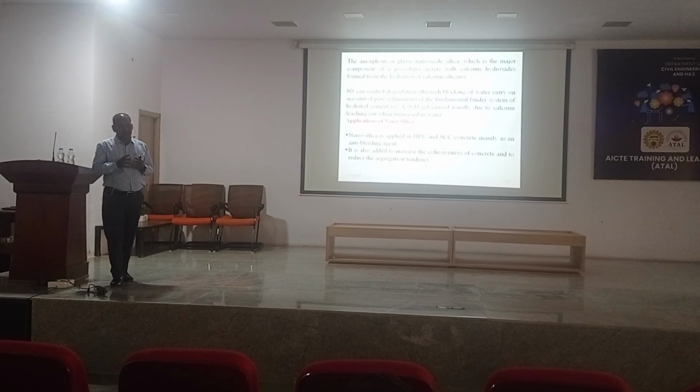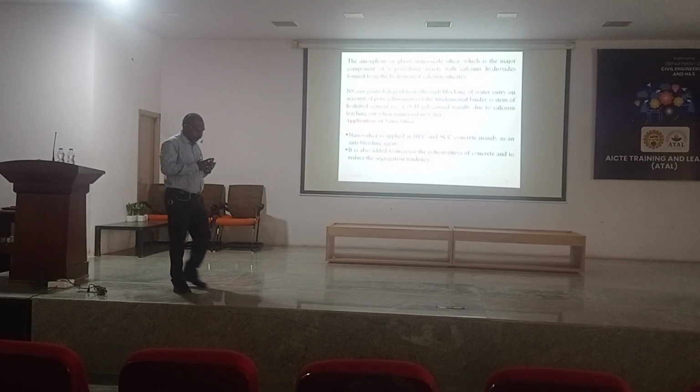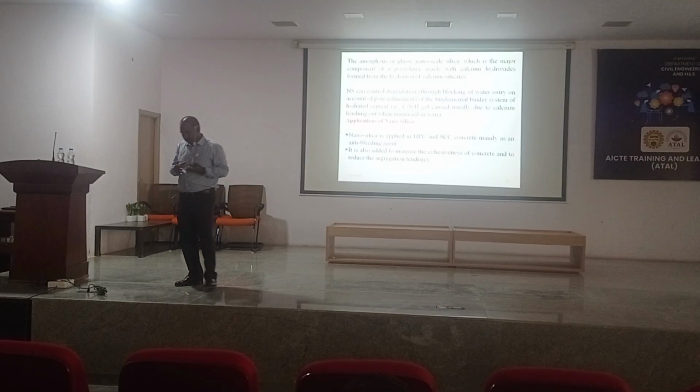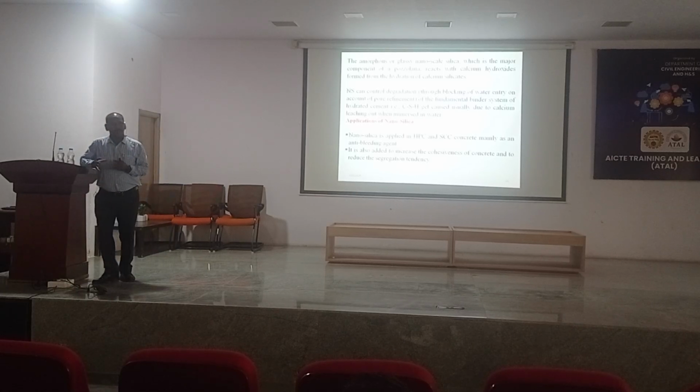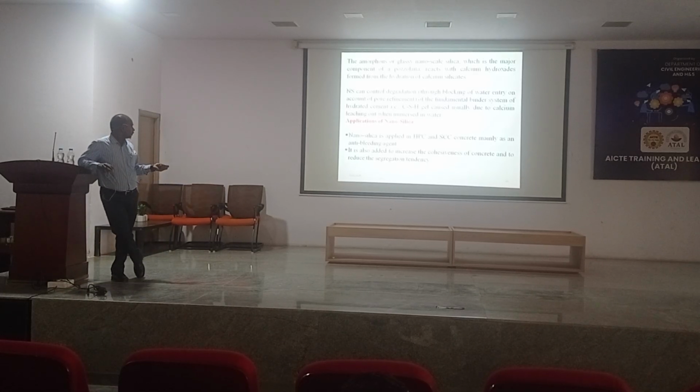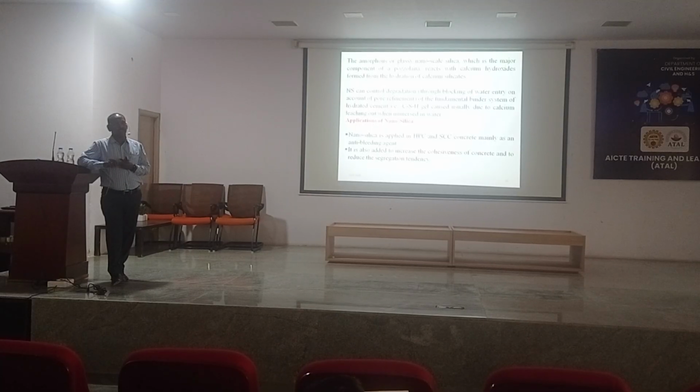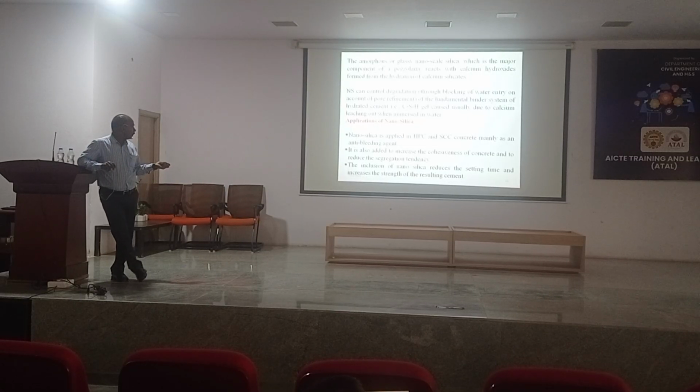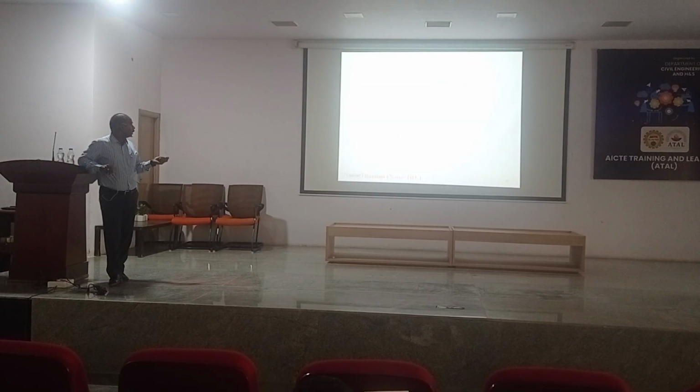Cohesiveness means that the cement matrix and the aggregate particles should be bonded to each other. That is called cohesiveness. When we have more cohesiveness, more bonding is there between the aggregate and cement paste, and there is no question of segregation. And inclusion of nanosilica reduces the setting time and increases the strength. These are the two parameters we want: decrease the setting time, increase the strength as required. That's why you can go for nanosilica.